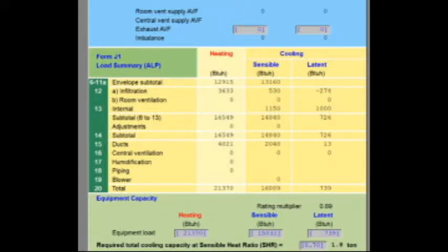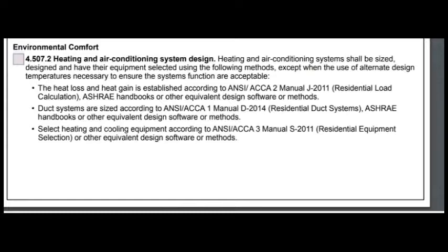And after we get that done, we know exactly what we need. We know how much total airflow we need, heating and cooling BTUs. That's when we can actually work with the HVAC contractor, find out the equipment that they prefer, and look at the different specifications on the different models the companies make, and find the one that has just the right amount of heating and airflow to dial in the system.